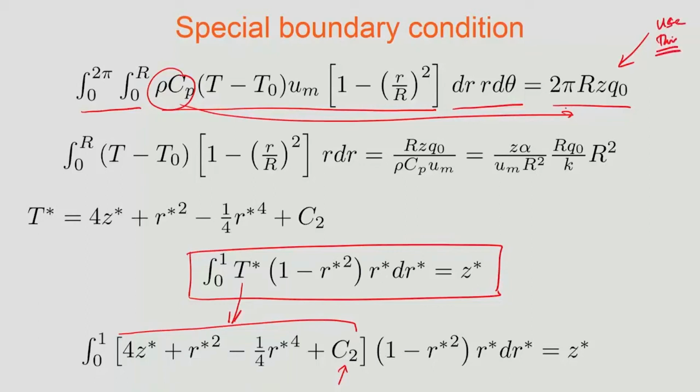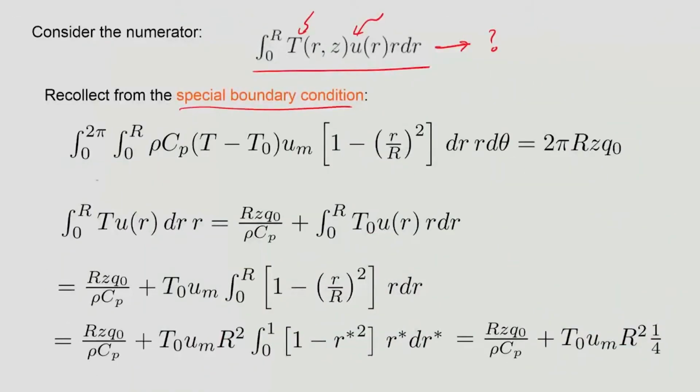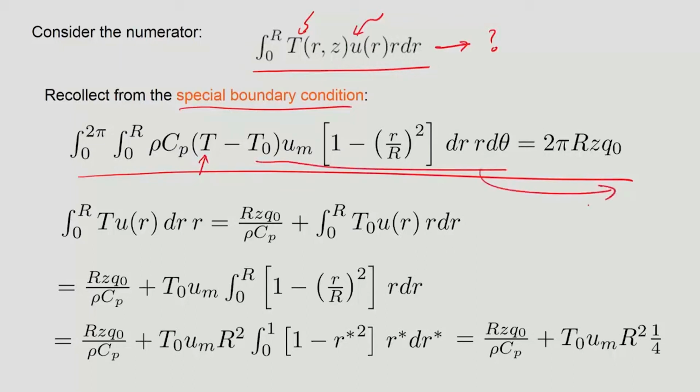We write this expression, bring it onto this slide, and we see that the expression is written, and what we wanted is only with respect to the temperature. So, take the rest of it onto the right hand side, which means that we can write the integral of T U r dr in this form, to the right hand side. Once you take it to the right hand side, it is a constant here, so you can go ahead and evaluate. We are actually postponing the evaluation of the bulk temperature, we are just using the expression as it is and reusing the analysis that we have done earlier.